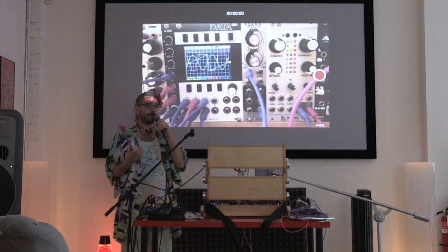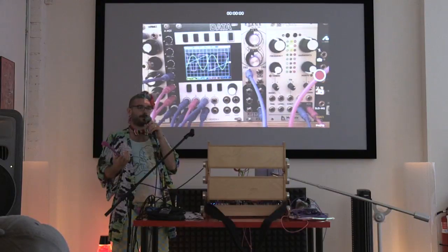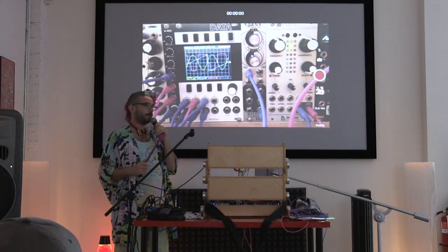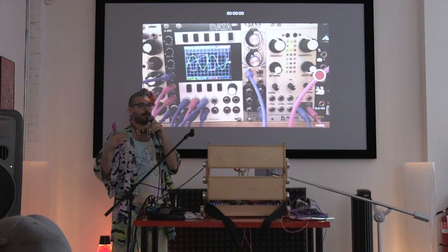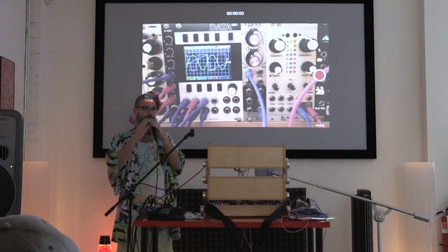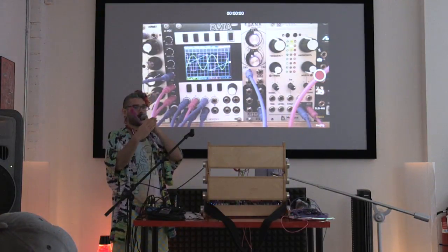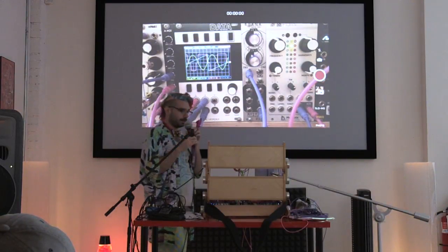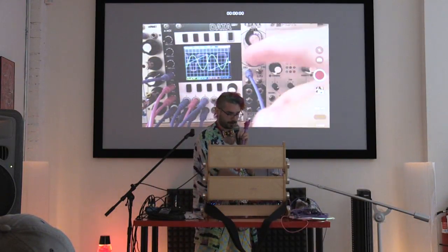If any of you are familiar with the Livewire audio frequency generator, it's one of the few VCOs that lets you pulse width modulate the positive and negative portion of the wave separately. That means you're kind of adding together 2 square waves and changing the width of each side independently. So this lets you do that with an arbitrary input.